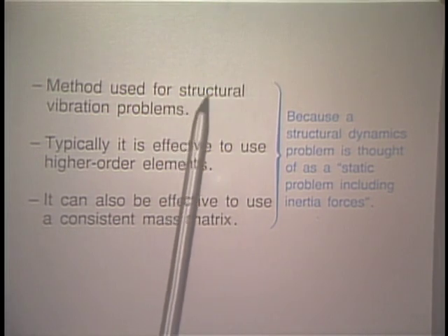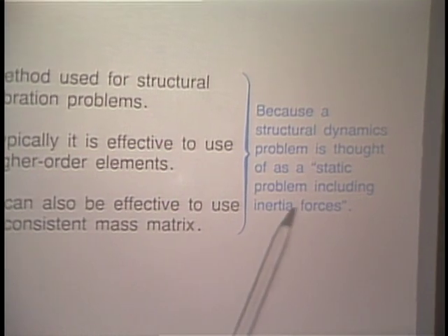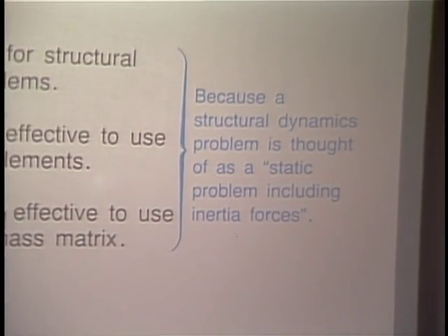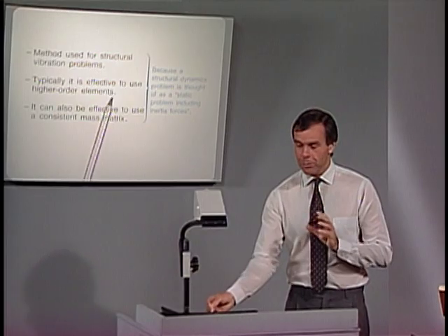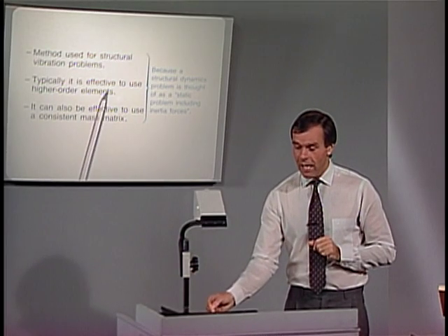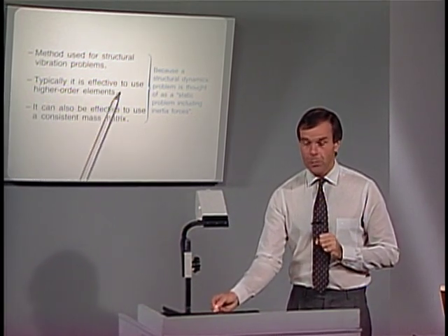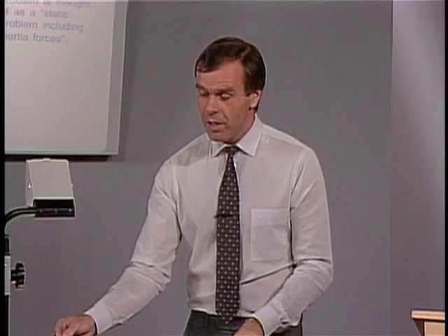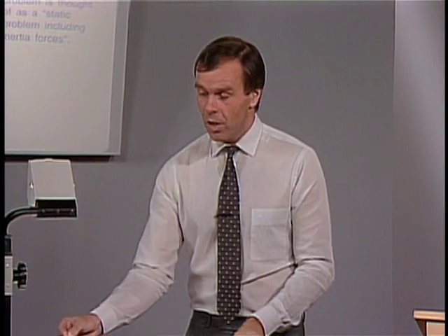Notice that a structural vibration problem can be thought of as a static problem including inertia forces, and we already have noted that in structural analysis of static problems, the higher order elements do quite well and sometimes much better than the low order elements. And for this reason, they also do quite well in dynamic analysis of structural vibration problems.